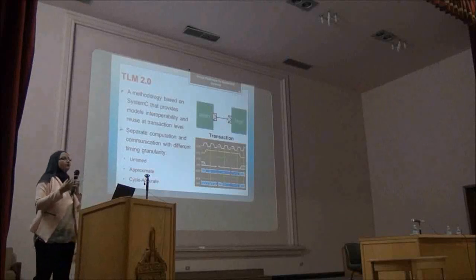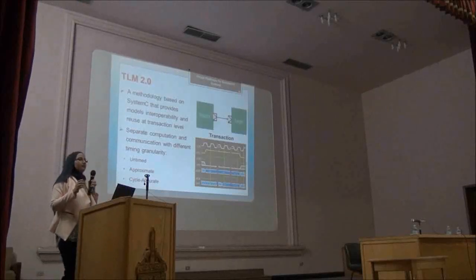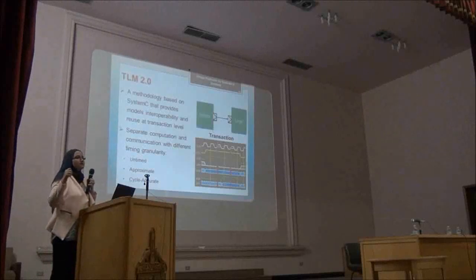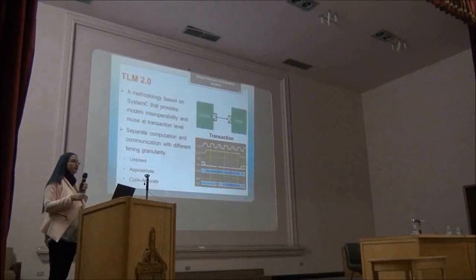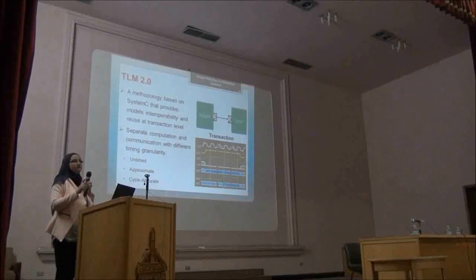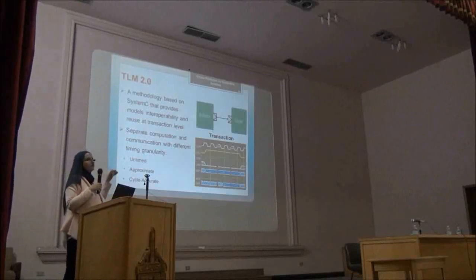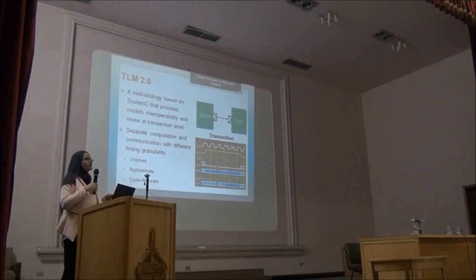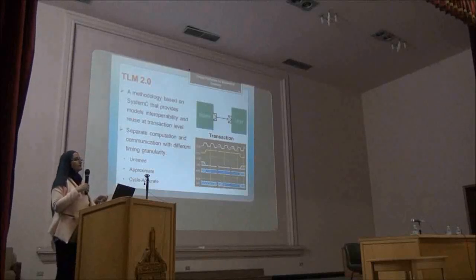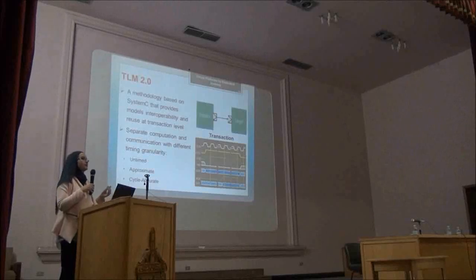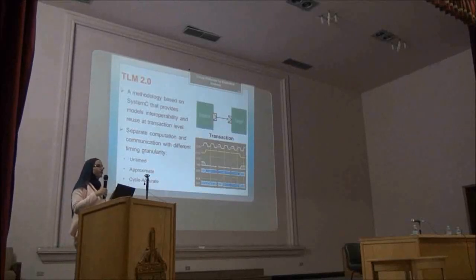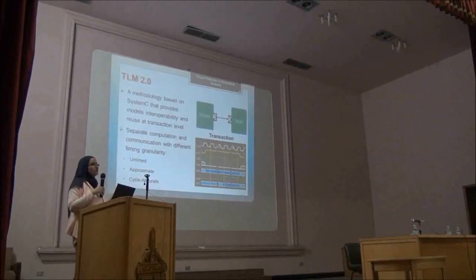So I don't really care at that level that when I'm programming a register, I'm raising the read signal, I'm raising the clock, I'm raising the read enable signal, I'm writing the exact address on the bus. I don't really care about the real processes on the bus signals. All I care about is that I'm doing a read from a register value, or a write to a register value, and I'm waiting for the same behavior as in the hardware to occur. If I'm reading the register now and it should contain 0, I should read back 0. If I'm writing the register to a specific value, it should be written to this value.